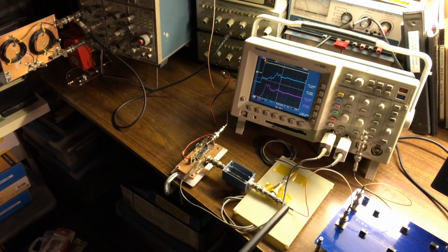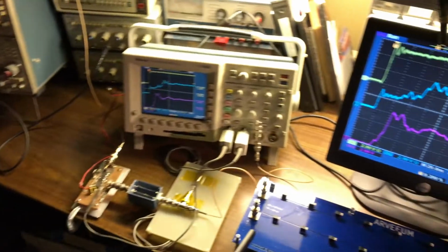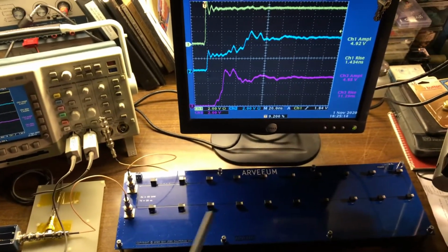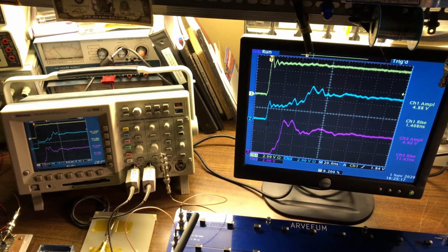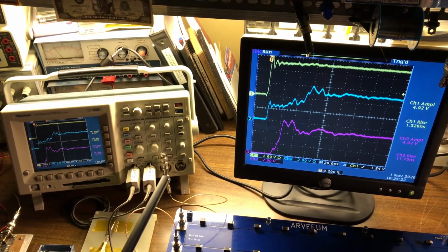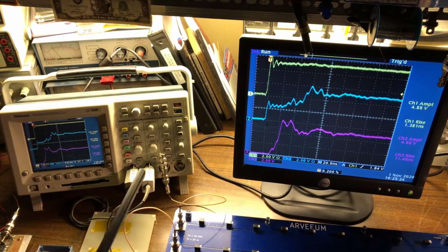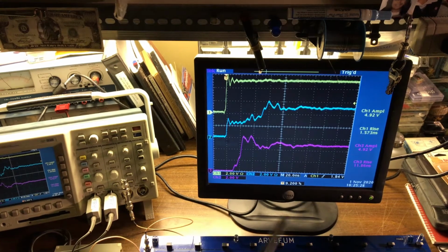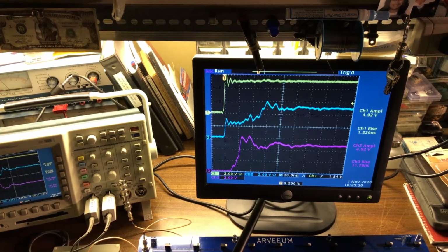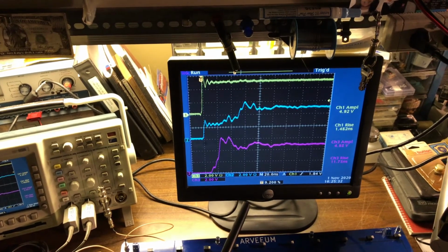and then right after the source termination resistor, the signal goes into the input of our test board, this board here, and the output of the test board goes into input 3 of the oscilloscope, and that signal is displayed as the magenta trace. Also, we have a display replicating the display of the oscilloscope, so we can see better with the camera, and that is the setup.